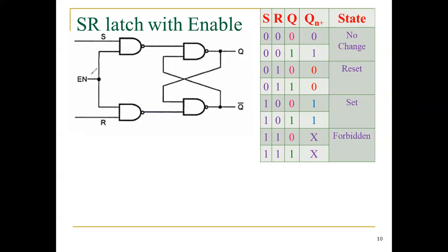Again, I retain the same thing. My enable pin now is also 1. Hence, one of the inputs equal to 1 here, that means N1 and N2. Now, my S input is also 1, R input is also 1. Please listen. Because of the truth table, this NAND gate output equal to 0 because all the inputs are 1. Similarly, here also 0. Okay.